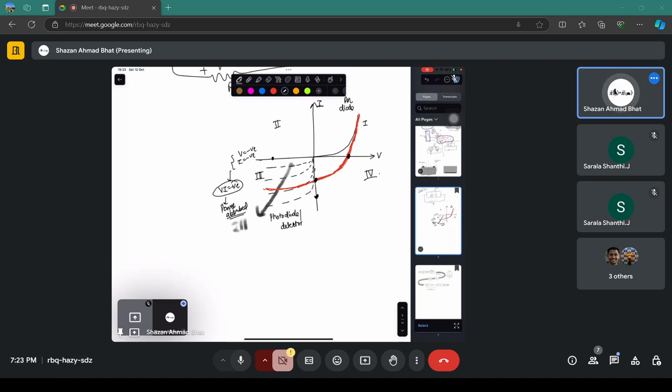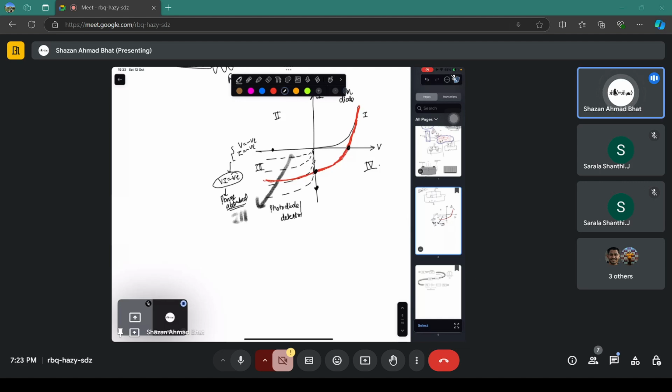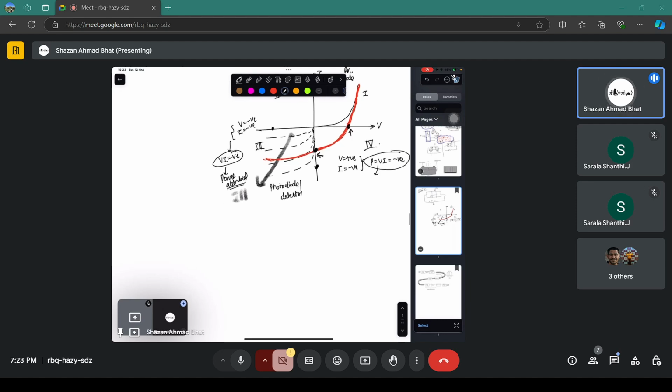You can basically call these some voltage. This is some value of current, and you see that here the voltage value is positive, the current value is negative. So the overall P, which is equivalent to V times I, will be negative. So that means the power is being given out from the system. So it is generated power.